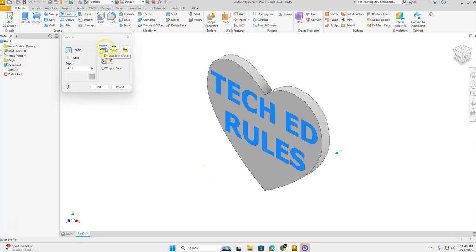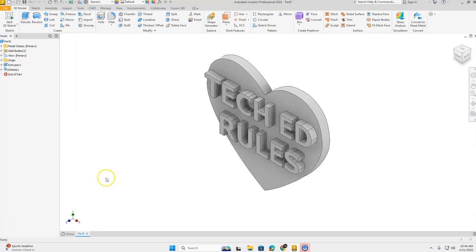I want to have emboss chosen, which is emboss from face. This one here, you can see the picture where it shows that it's raising up. And then click OK. And there it is. My text is embossed in there, and that looks great.